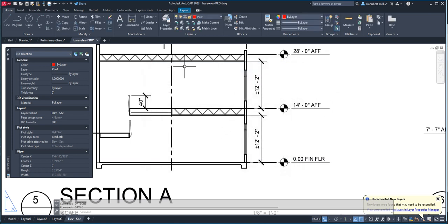So I'm going to test that. I'm going to click on Text, single line text. I'm going to select here, and then I'm going to specify just a 1/8 height. I'm going to accept that, and then I'm going to simply type 0.20, and then 1/8, enter, and then 120, and I'm going to test it. So ARCHITXT in capital letters. Oh, looks like it was loaded. Okay, so I'm going to erase that.